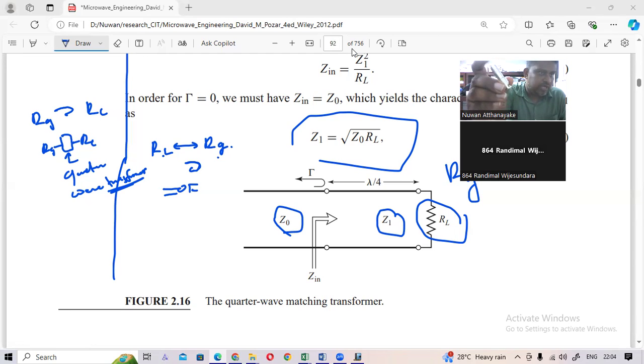So you can connect them. Actually, this is in here. You can see there is an inner conductor and this is the outer conductor. So you have to solder the cable to this connector. Then you can make a coaxial cable with this connector. So this is a BNC connector, and this is another type of connector. We call this a DIN connector.